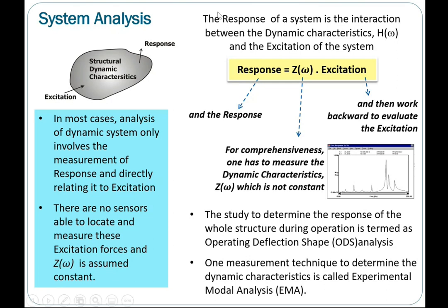That is an experimental technique called operating deflection shapes analysis, ODS, which you can use to determine the overall movements or overall response of the machines during operations.